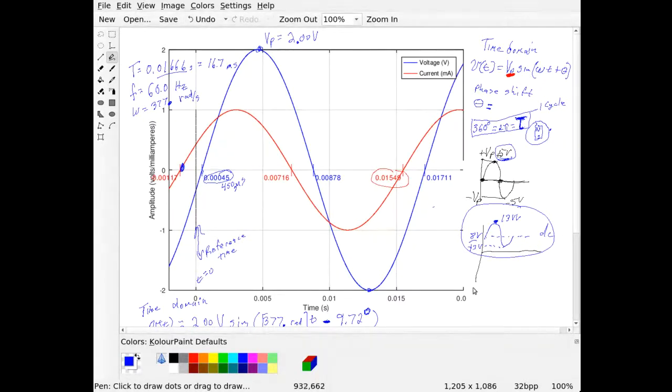So if we wanted to write that, we would actually write the voltage waveform as being a constant DC. Okay, so it would be 8 volts constant DC plus, I don't really have room here, but plus the sine wave of 5 volts times sine, whatever the frequency was, sine 377t or whatever the frequency would be.